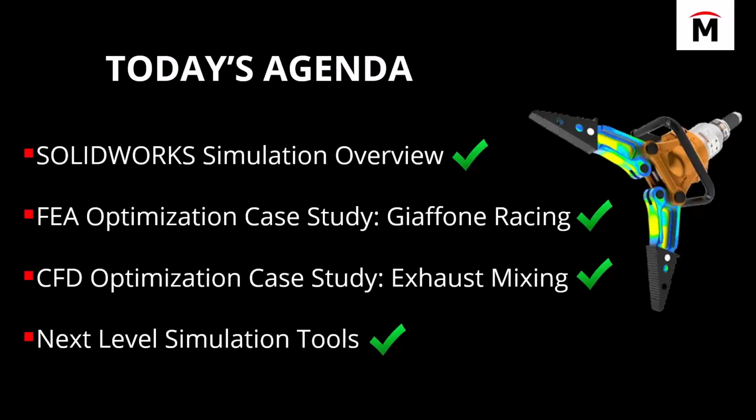A lot of times you'll set up a more complex study in SolidWorks nonlinear, and maybe it doesn't solve all the way through. Maybe it only solves like 80%. And that can certainly happen if you have, let's say, really high strains. For instance, you can't inflate a balloon in SolidWorks Simulation. You'll find some point where those elements that have meshed the balloon are stretching too much, and the software will just run out of what it can do.